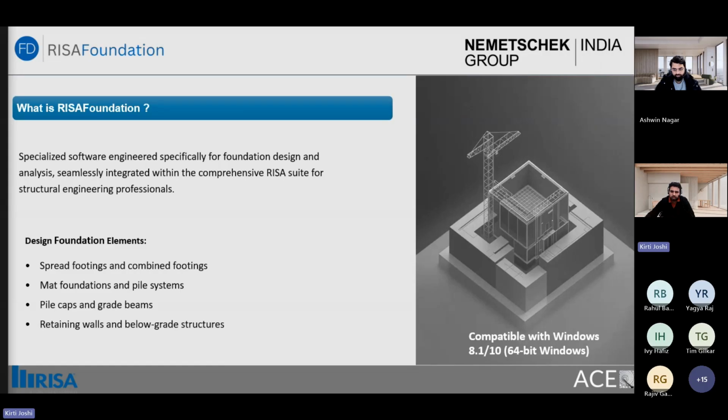This software can work independently, but at the same time, it is easily integrated with the RISA suite, specifically RISA 3D and RISA Flow. For example, if you have completed your superstructure analysis in RISA 3D, then you can integrate the RISA 3D model with RISA Foundation, where the reactions come directly into the foundation model.